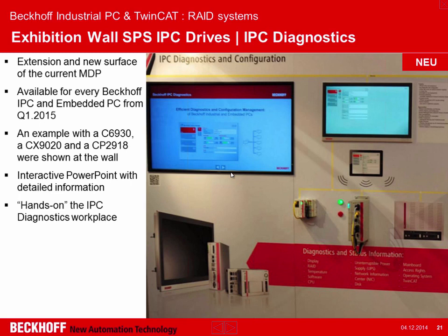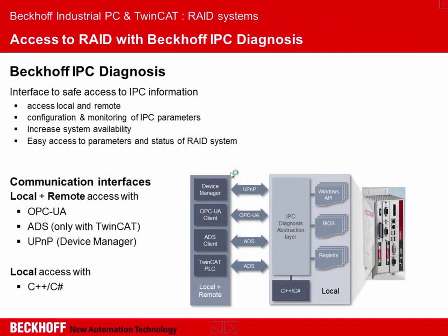Yeah, the RAID controller diagnostics is completely integrated in the IPC diagnostics, and we have different ways that you can use this diagnostic information. You see on the bottom that we have different ways from the outside to get the information from the inside, so from the Windows API, from the BIOS, from the registry and other things. And RAID diagnostics is integrated in the system.